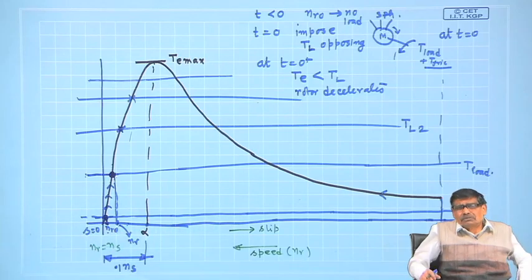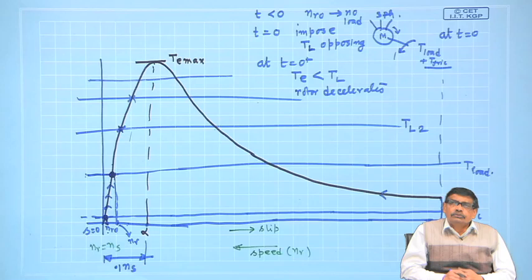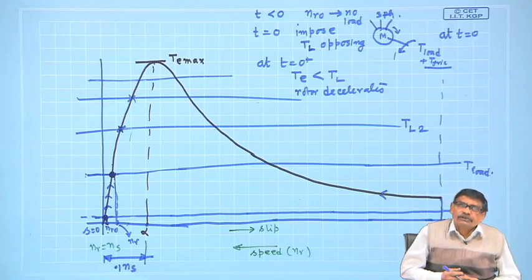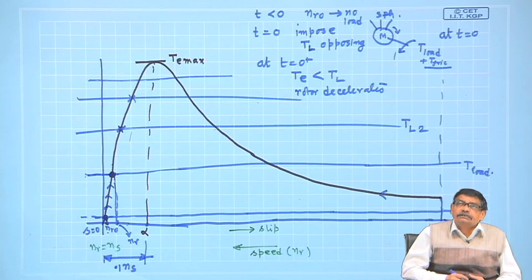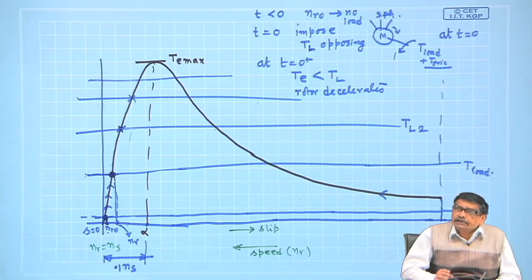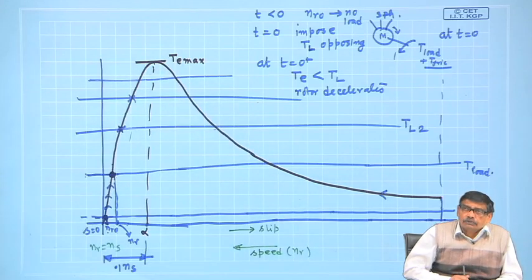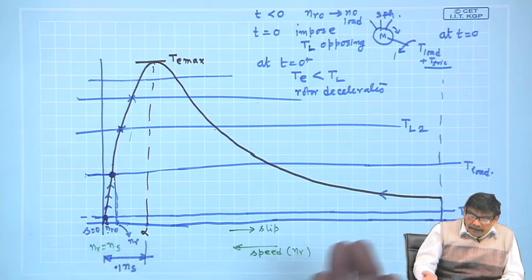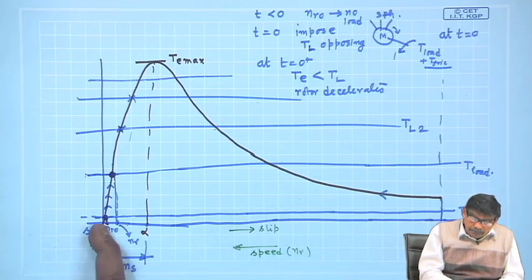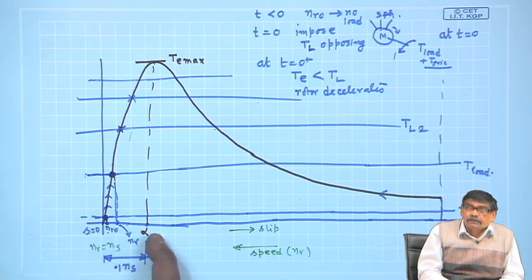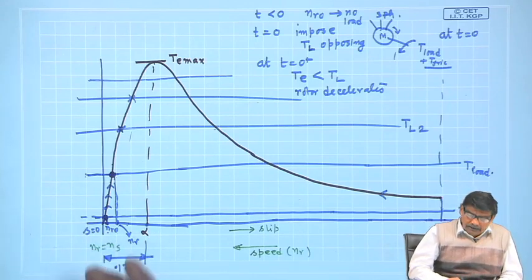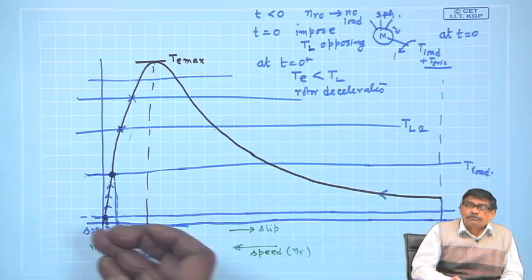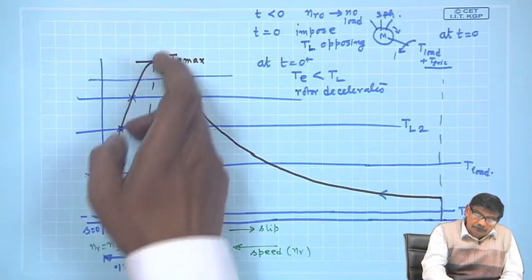Therefore, in earlier days people used to say that an induction motor is almost a constant speed motor, like a DC shunt motor. If you do not touch the field winding of a DC shunt motor, variation of speed from no load to full load is very little, almost like a constant speed motor. If it is a 4 pole 50 hertz machine, it is 1500 RPM, and 10% of that, 0.1, means the speed may change by only 150 RPM or so as you go towards that side.